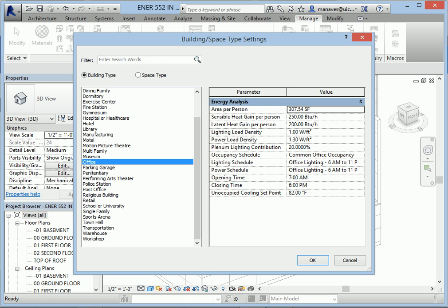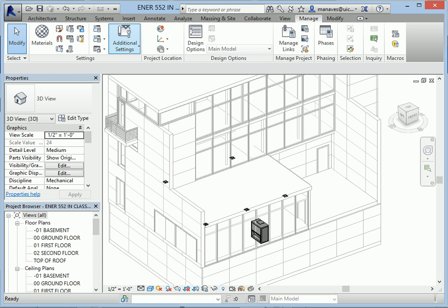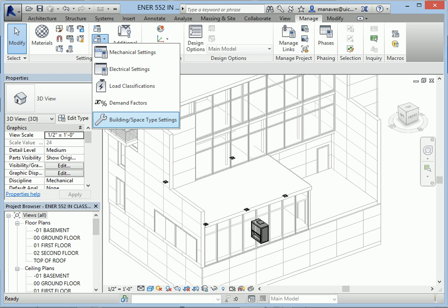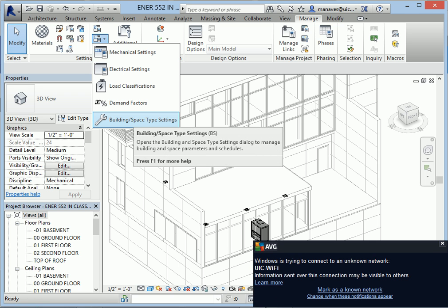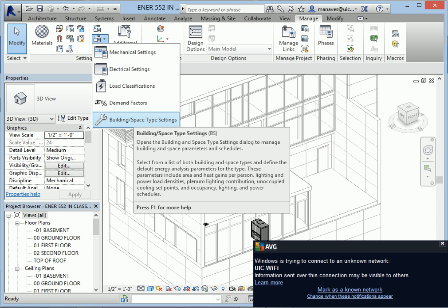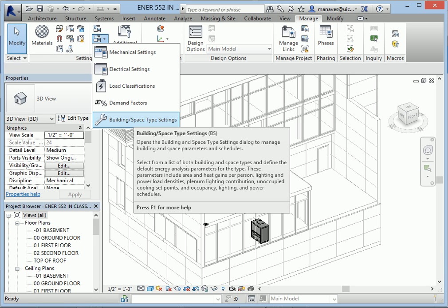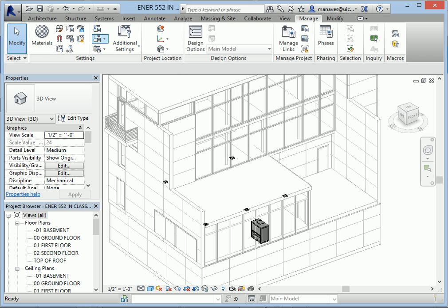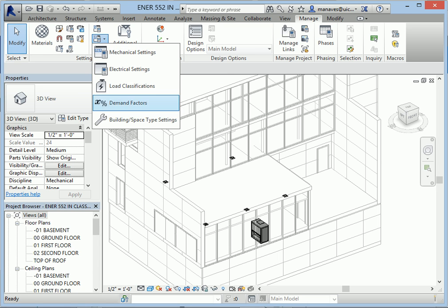Okay. So it's right. Can you pick office? Yeah, pick office, of course. It's right here. BS is obviously the shortcut. Building settings. It looks a little different, but you're looking for that. So it's under MEP. So there should be like this little icon that says MEP settings, and it's the wrench.